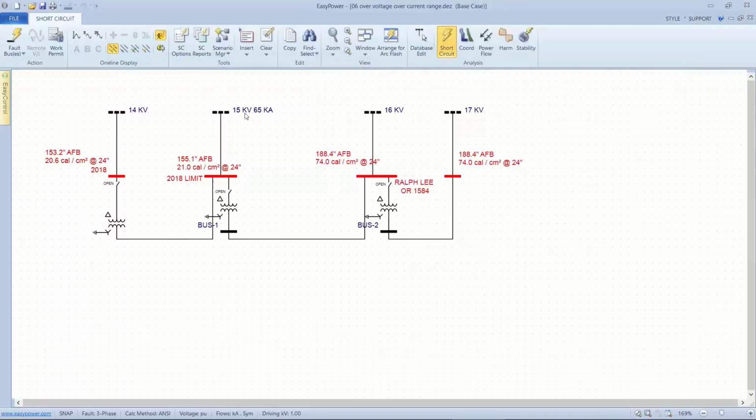If you've followed my presentations before, that application is actually meant for a single phase comparison, and at 15,000 volts we get what would be considered a rational comparison between the limit and 10% and 20% above for a single line to ground. If we compare that against a three-phase limit, then it's using that multiplier, and we're getting 3 times that.